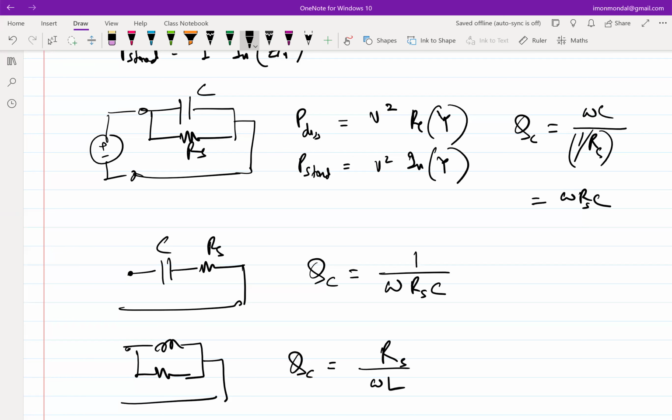But as it turns out, for a certain value of L, if you choose, let's say 1 nanohenry of inductance, you kind of get 1 ohm or 2 ohm of resistance free with it. You cannot do anything about it. So which essentially means that in the denominator, you only have this L or C as a free variable. Everything else is fixed. Right? And since you cannot do anything about it, you might as well go along reducing the number of things that you cannot change in your expression, right?